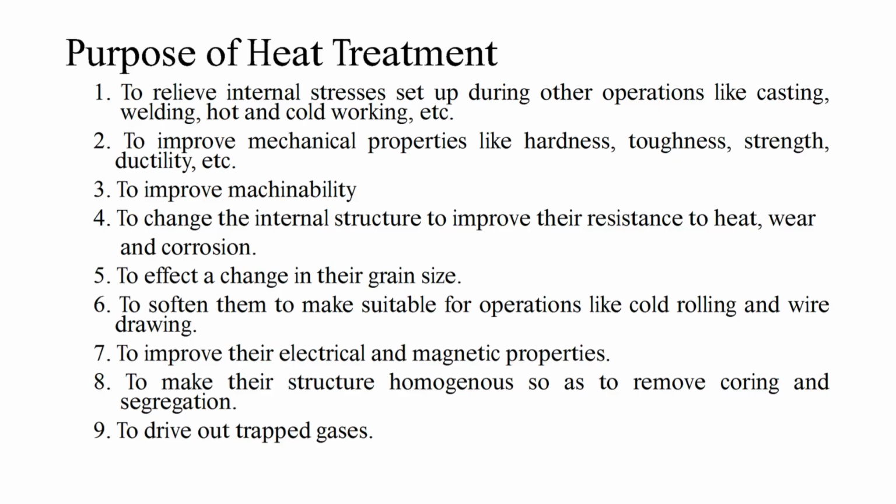Let's explore. 1. To relieve internal stresses set up during other operations like casting, welding, or hot and cold working. 2. To improve mechanical properties like hardness, toughness, strength, and ductility. 3. To improve machinability. 4. To change the internal structure to improve resistance to heat, wear, and corrosion. 5. To effect a change in their grain size. 6. To soften them, making them suitable for operations like cold rolling and wire drawing.